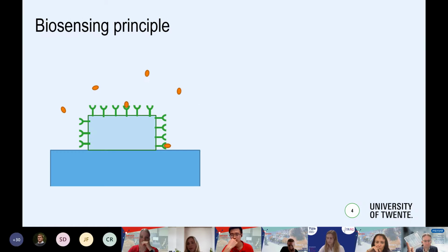So, how does it work? The key is in the chip, comprising a group of waveguides and microring resonators where the light is confined. The ring acts as a filter, so specific wavelengths, depending on the refractive index of the surroundings of the microring resonators, enter and resonate and then build up in intensity inside the rings.